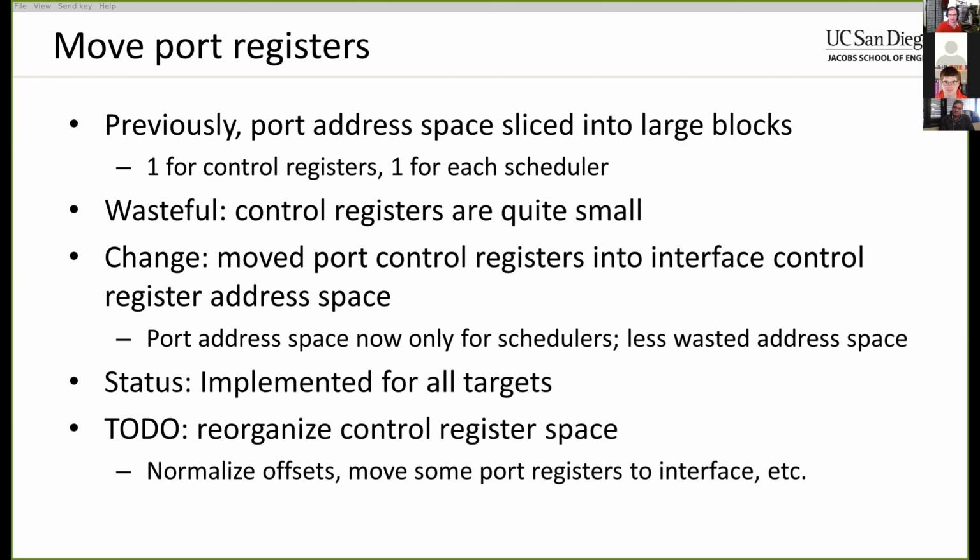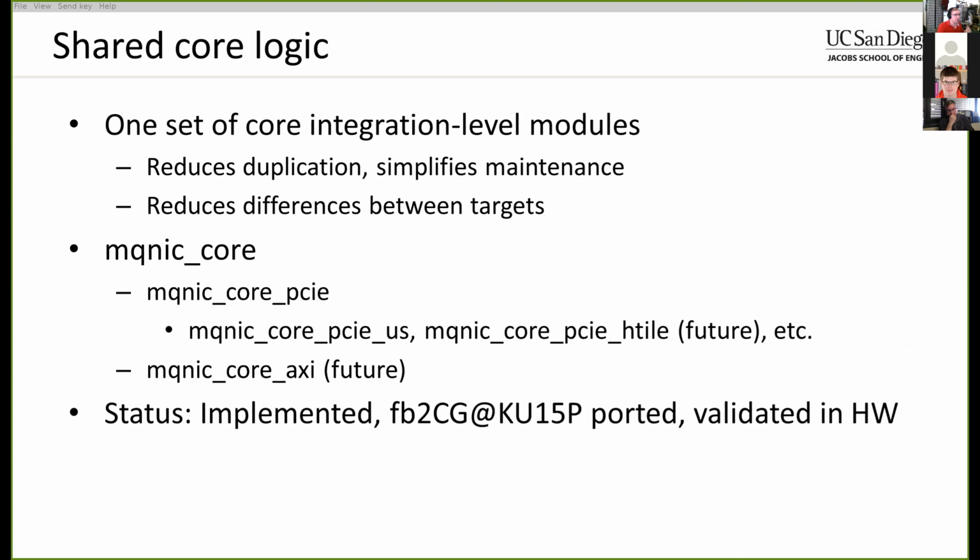And eventually what I want to do is reorganize the register space a little bit more to normalize all the offsets, and also to move a few of the port registers into the interface. But that's probably going to wait until we do the shared interface data path, where basically most of the port registers are going away because all of that logic is moving into the interface.